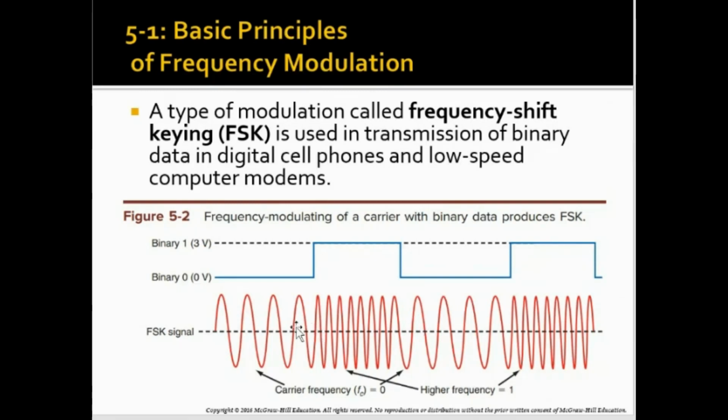So therefore, what you have is only two frequencies, because frequency modulation is supposed to change based on the amplitude. So now you have, let's say, 0 volts, which has one frequency. When it shifts to a higher voltage in your message signal, the frequency changes to another frequency, but remains there because your amplitude is constant.